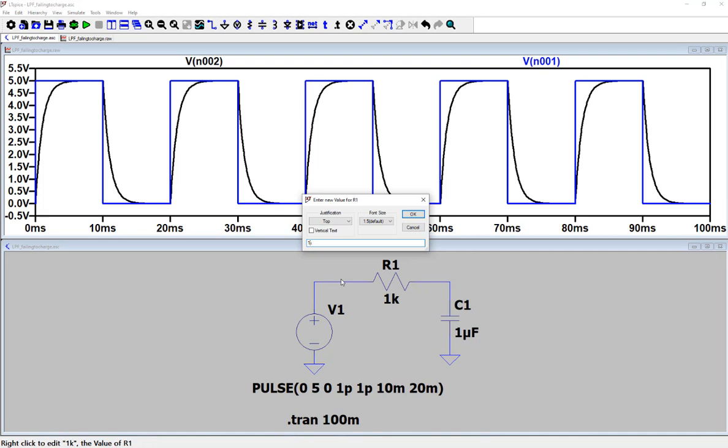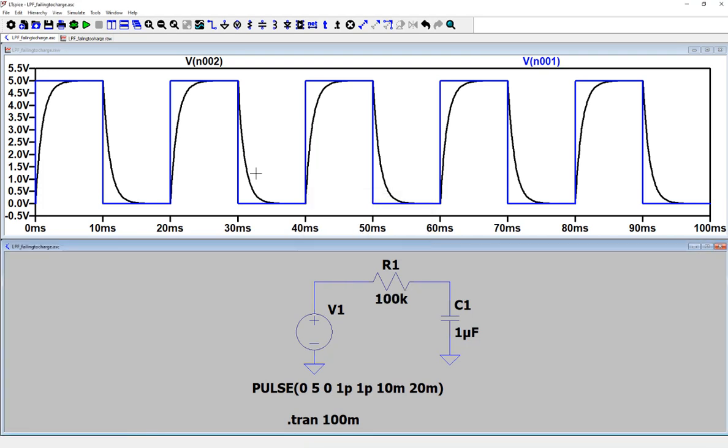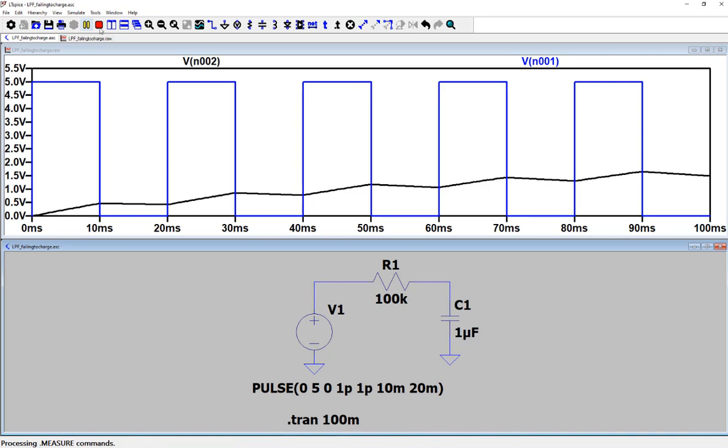If your signal is too fast, or we just change the circuit, so the signal is too fast for the circuit, it's not able to fully charge the top, and then it starts discharging, okay? That's why it's not able to maintain that oscillation, so it keeps accumulating charges in this manner. So eventually, can you expect what's really happening? Because I'm only showing you 5 periods. Is this eventually going to fully charge to the whole 5 volts, or will it stay somewhere?